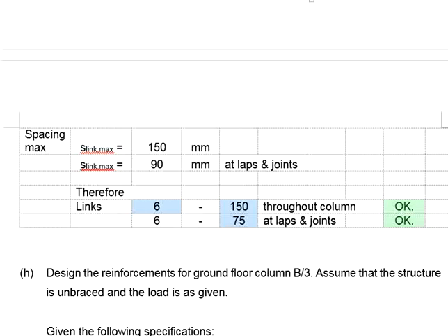However, considering the practicality, where the local industry refers to the dimensions in inches, while we are designing in SI units, maybe we just make the dimensions in intervals of 25 mm. 25 mm is equal to 1 inch.